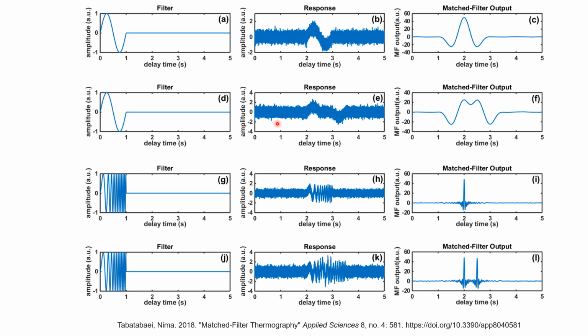And here we can see the noise response at the receiver, and we can see that it's very hard to make a decision. But once you go through the matched filter, you look for the signal of interest and you get the following response. You need to take the reading at the proper timing.